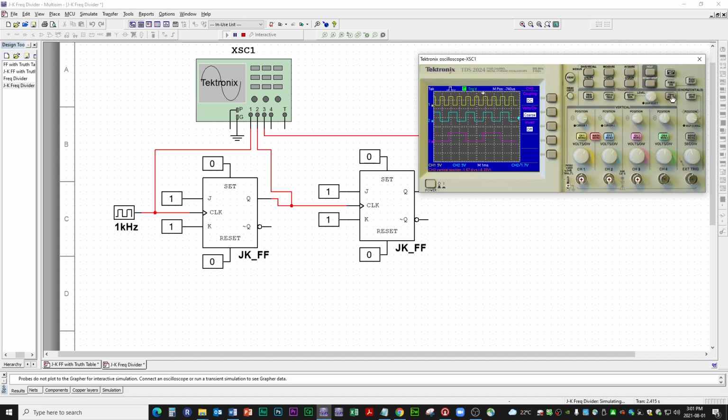And we're going to call up the trigger menu, and we're going to take a sample of this channel 3, because it doesn't look like it wants to settle down. So change the source for triggering to channel 3. Oh, and we just have the trigger here. So all 3 signals are settled down. Okay, well, look at this. This frequency is half of that, and this frequency is half of that. Look at that. This is amazing.